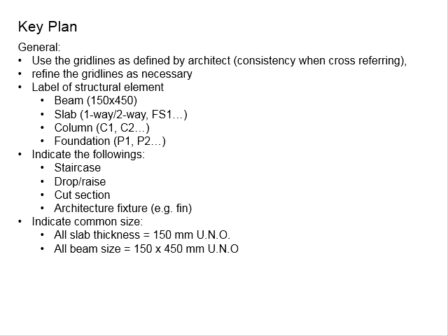Make sure the size of the beam does not exceed the allowable space within the ceiling. You don't want your beam suddenly appearing out of the ceiling, and this is going to affect the aesthetic part of the building. Normally, the architect will not compromise on this.